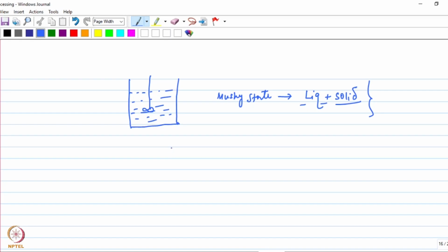Okay, and this property of a material, if you process a metal through a route like this, you basically break down the dendritic structure and you can expect an equiaxed microstructure in the solidified material, if you do this stirring in the two-phase region. Okay, so this microstructure can be even preserved even when you heat the material and melt it. Okay, so that property of a material to preserve that equiaxed microstructure even during remelting is known as thixotropy.